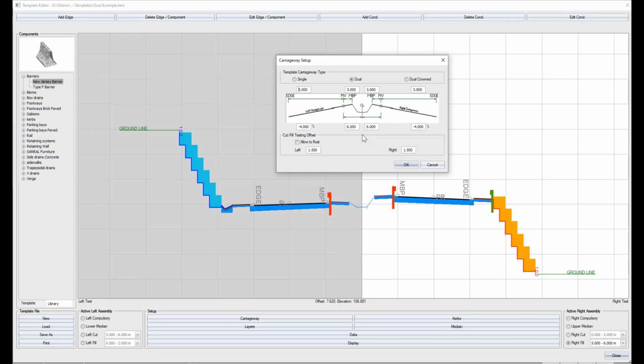When the road width changes due to lane widening or the crossfall grade changes due to super elevation, it is not required to specify a different template. However, if need be, Civil Designer caters for up to 200 different templates per road, and additional templates can be added to the extremities of templates already applied.